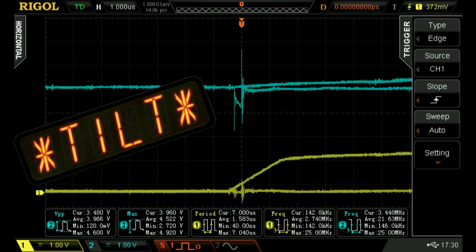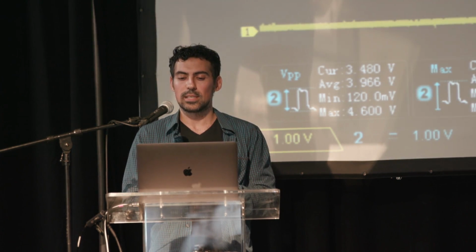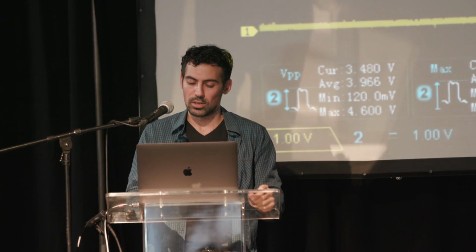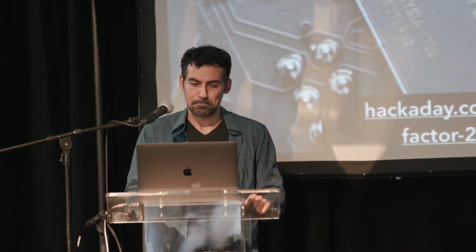By removing the voltage for just a moment, just an instruction, and removing the bypass capacitors so the CPU starves, you will then skip an instruction, assuming that your glitch voltage is low enough and your pulse width is long or short enough. You will have to play with this stuff, but the nice thing about devices like microcontrollers and FPGAs is that you can program them and you can make them do really cool stuff.